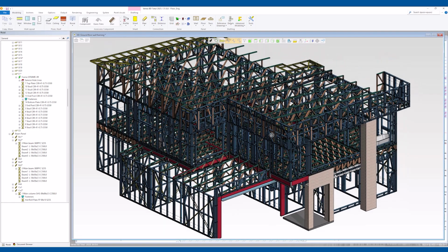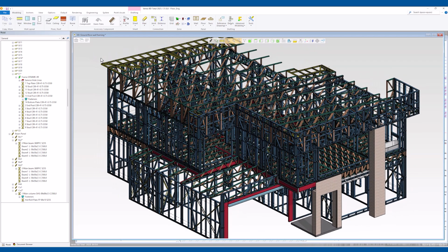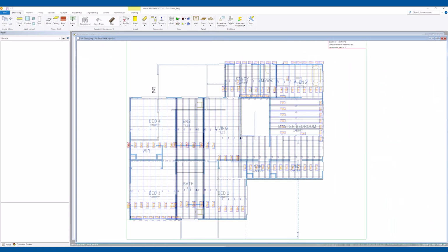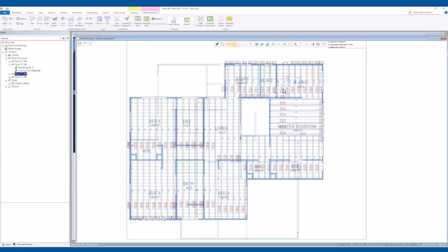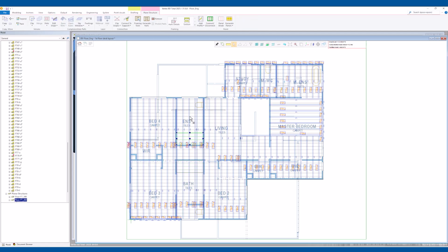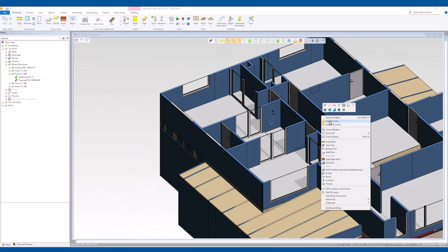Hello everyone. In this demo, I'm going to walk you through the floor truss engineering process in Vertex BD. Let's start by switching over to the 2D drawing and opening the floor truss layout. This is a real project that has been built, and from the architectural plan, we know there are some wet areas with step downs.